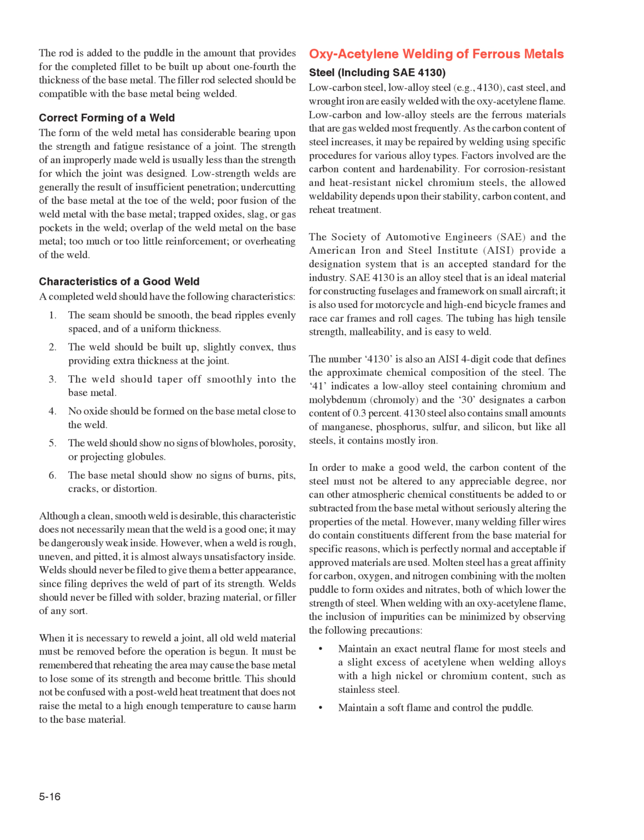Welds should never be filed to give them a better appearance, since filing deprives the weld of part of its strength. Welds should never be filled with solder, brazing material, or filler of any sort. When it is necessary to re-weld a joint, all old weld material must be removed before the operation is begun.